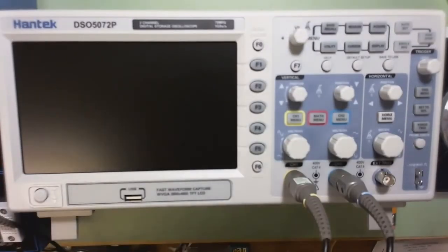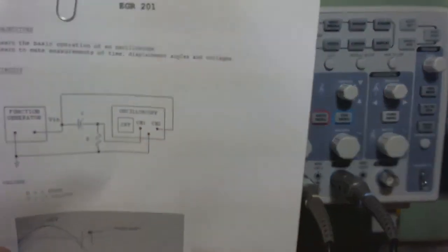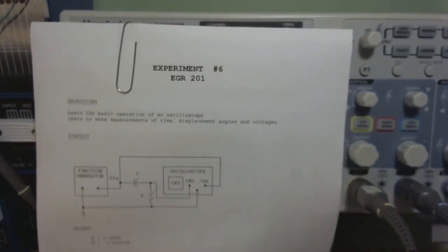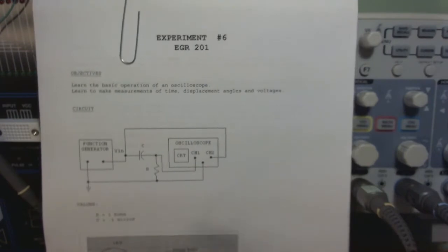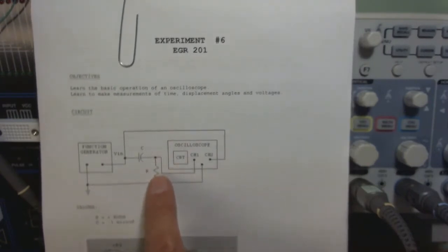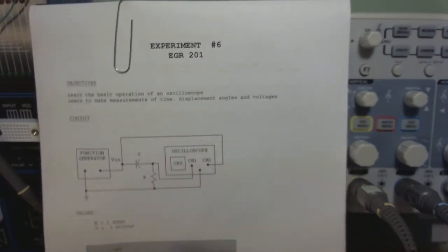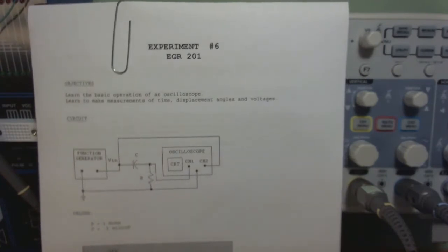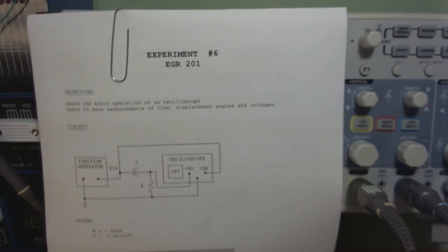Okay. So there's our oscilloscope. Maybe before I turn things on, let me talk about the lab itself now that we can see this a little better. You're going to have this in hard copy form. It's a little hard to see here, but basically this is our circuit. We've got a capacitor and a resistor, and we're measuring with channel 1 the voltage across the resistor. We're measuring with channel 2 the voltage across both of them. So we'll consider channel 2 as our input voltage, and channel 1, the voltage across the resistor, as the output voltage. And before we're done, we'll switch the location of the resistor and the capacitor.